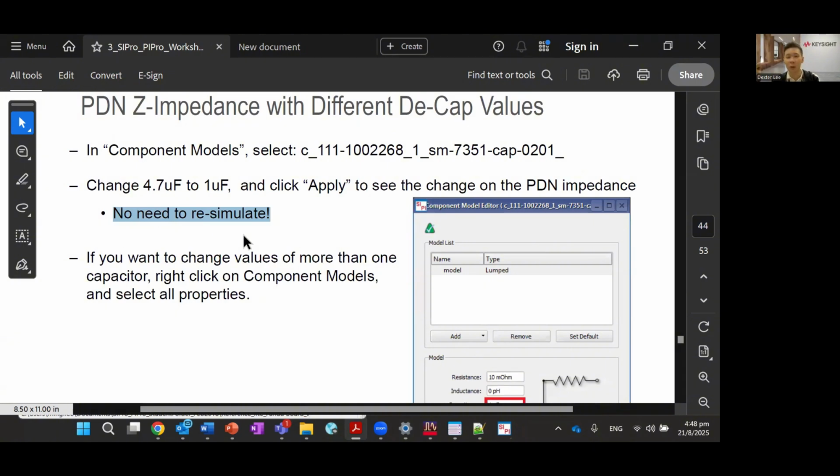You can disable decoupling capacitors, the profile will change immediately, and this is something that is useful for designers because they want to know, is it necessary to place a decoupling capacitor there during their design? Or should they change to another value of decoupling capacitors? I call this the design exploration, where they tweak different values and see how it impacts the impedance. From then, the designers can make an informed decision what component they should change to, or should they even place it there.